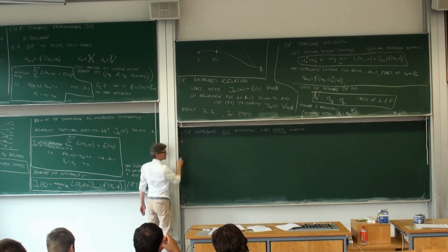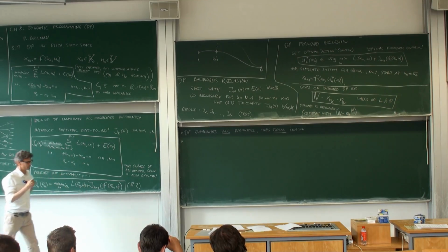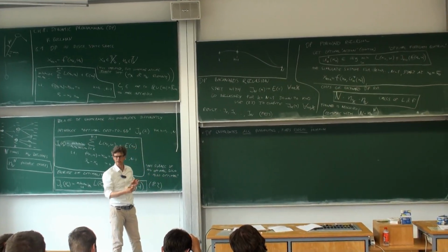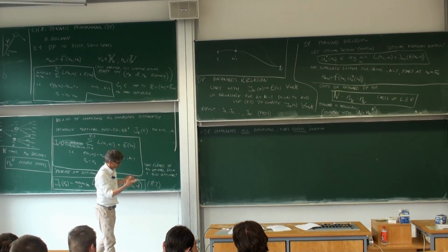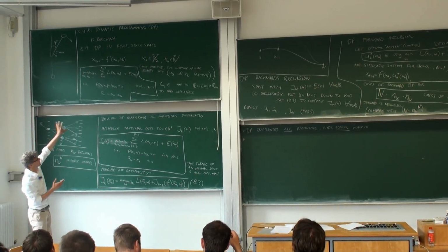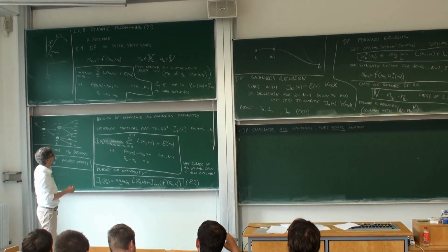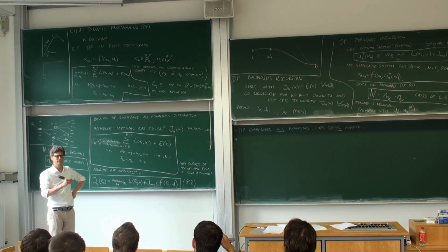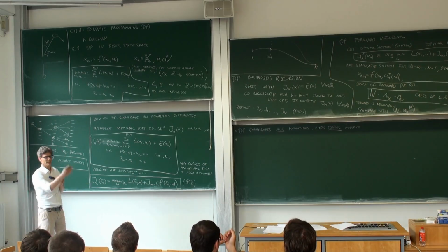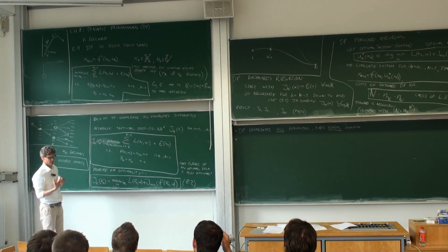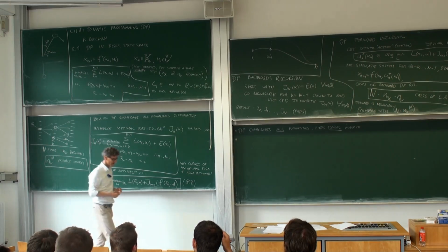The second really nice feature, I think, is also very worth thinking about: it delivers not only just one trajectory, but it delivers even a feedback control law. So if someone says, please solve that problem, and you have solved it with DP, and then the same person says, okay, by the way, the initial value has changed now, can you solve that problem again? And you say, yeah, and you have your solution. Because if you have the storage of your cost-to-go function, you can very quickly get back the forward solution by forward sweep.